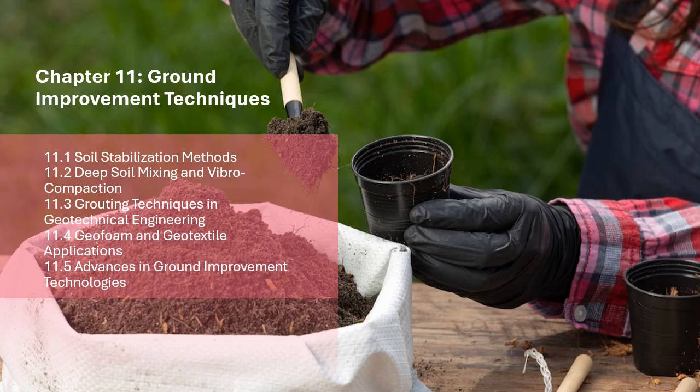11.3 Grouting Techniques in Geotechnical Engineering. Grouting is a ground improvement technique that involves injecting a fluid or semi-fluid material, called grout, into soil or rock formations to enhance their properties. The injected grout fills voids, cracks, and fractures in the soil or rock, improving their strength, stability, permeability, and other geotechnical characteristics.